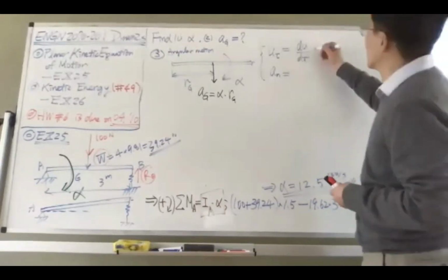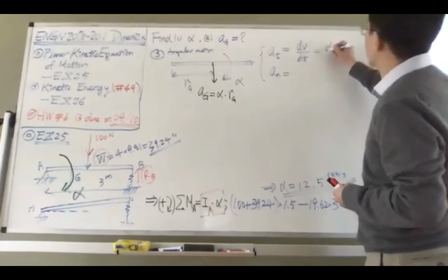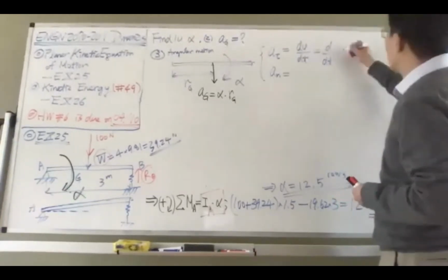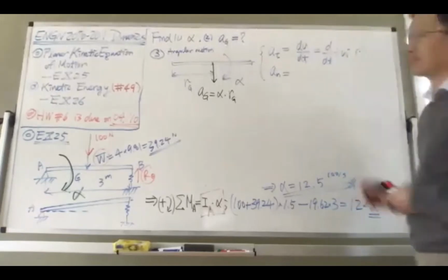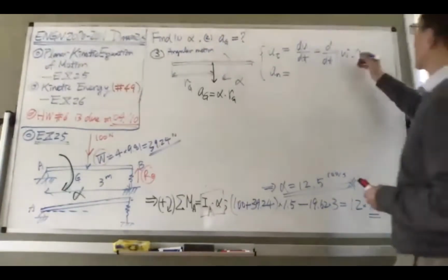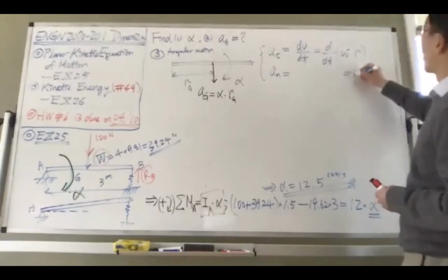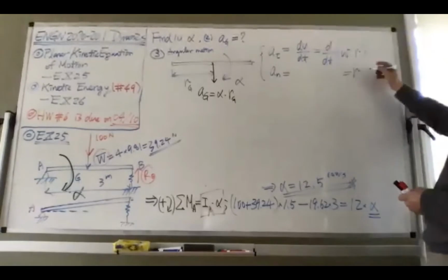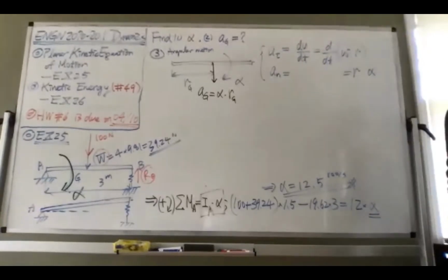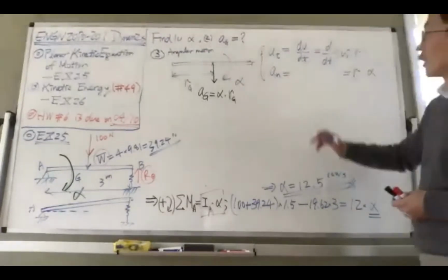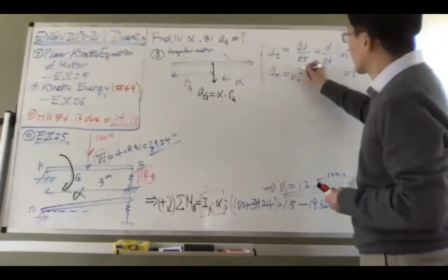And the velocity here is actually, what's dV/dt? The velocity here is actually omega times R, right? So here, R doesn't change. So that means it just becomes d omega/dt, which is alpha. That's from normal and tangential component. And the normal component, as we already know, is omega squared times R.